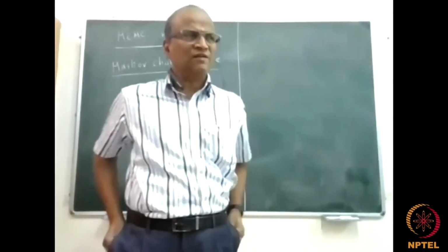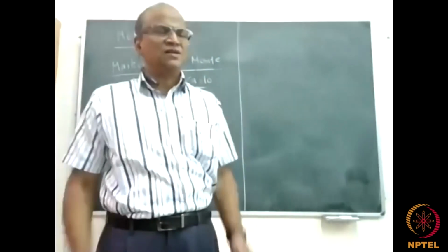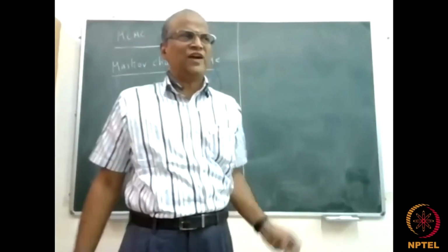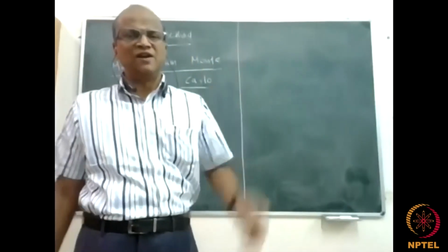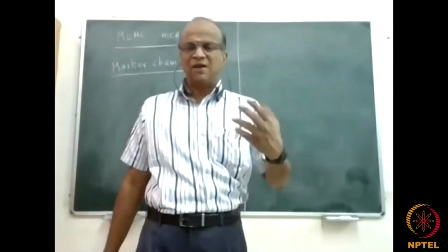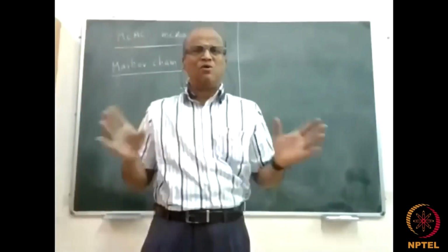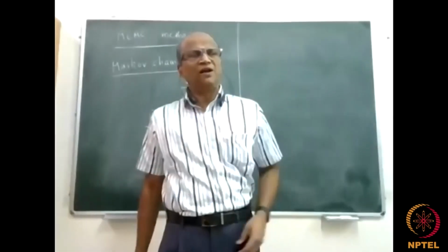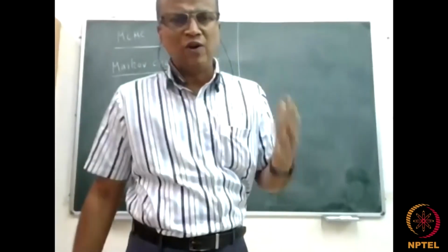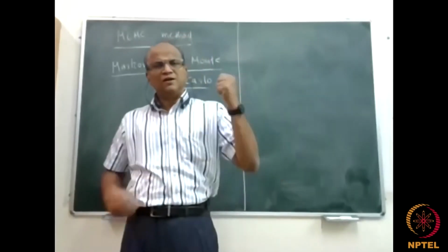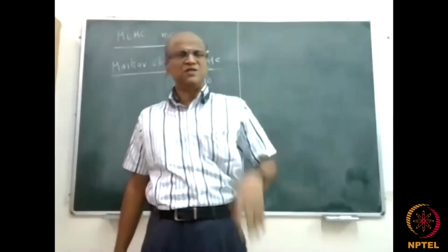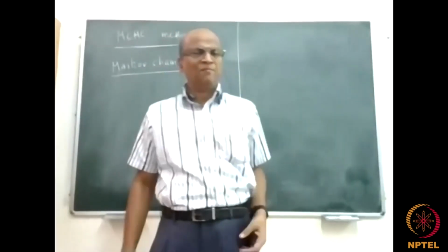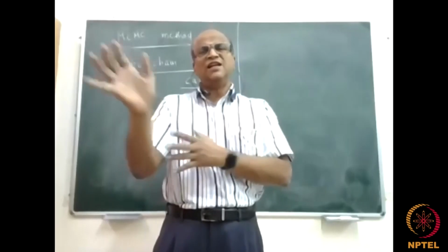So Suraj also demonstrated. We wanted to find out the Q, the heat flux, from the set of temperatures in a slab. So we just divided the Q from 500 to 1500 or whatever in steps of 100. And then it was pre-assigned, it was arbitrary. The bounds can be decided based on prior experience, but these divisions were arbitrary. And for each of these points, you ran the forward model, got the simulated temperatures, compared to the experimental temperatures, got e to the power of minus chi square by 2, put your prior and so on. But there should be a more scientific way of generating these samples.